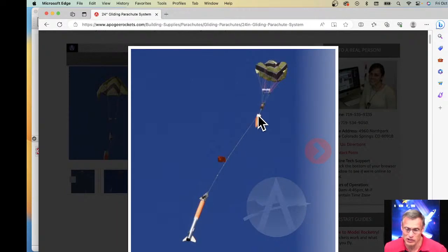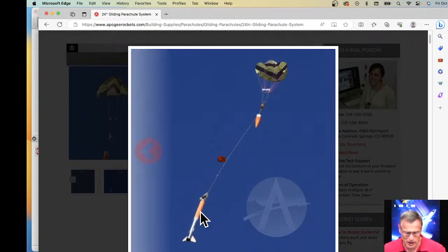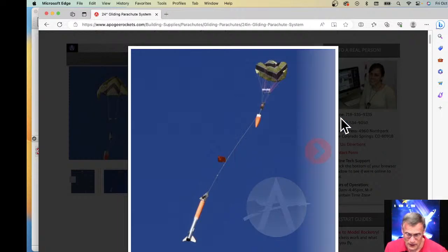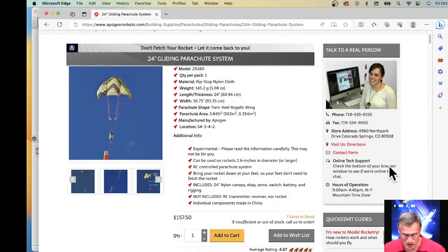Head end means that you're putting the electronics inside the nose. Where normally in a dual deployment rocket, the electronics is right in the middle. And there's an advantage for that because it allows you to use the motor's ejection charge as a backup. When you're doing head end, it's a little bit more complicated, but it can still be done. But RockSim does not care.